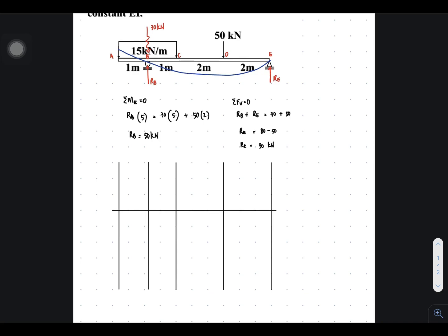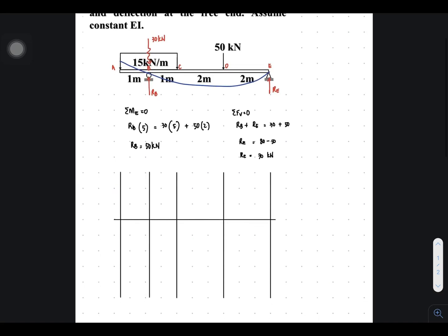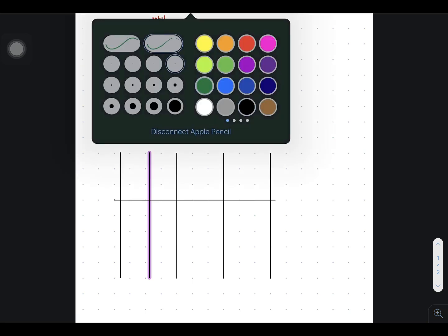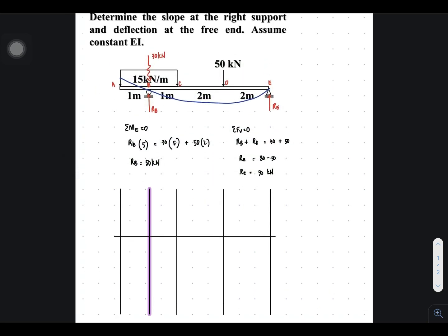So, a simple tip, whenever you are looking for deflection, whenever it is an overhanging beam, always rotate at the interior support. So always rotate. Why? Because it's going to separate your load diagram later on. Since it's an interior support, it can become an internal hinge later on. So better that you rotate it there. So there. We're going to proceed with the moment by parts.